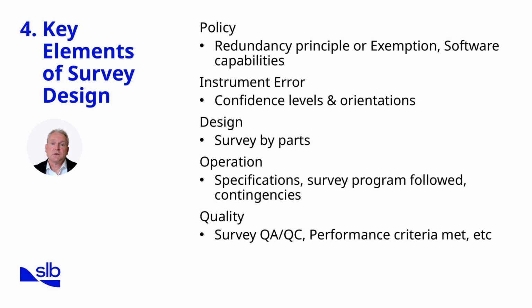Finally, we consider quality control. Survey QA/QC processes are essential to verify that the data meet performance criteria. Errors or poor quality surveys can result in misplacement, potential collision risks, or missed reservoir targets.